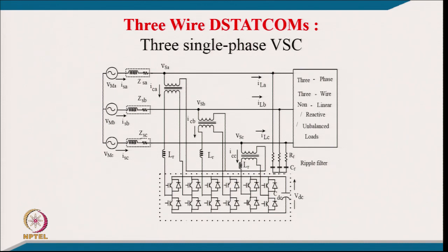You can have independent control of each phase current, and now you can use unipolar switching here. With unipolar switching, the benefit is that the switching frequency can be reduced to half compared to the ripple frequency of the current going through the LR. And moreover, the DC link voltage also reduces here, much lower, even if you put a unity gain turns ratio transformer.